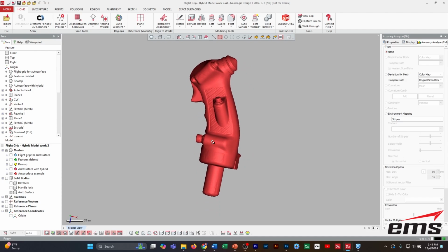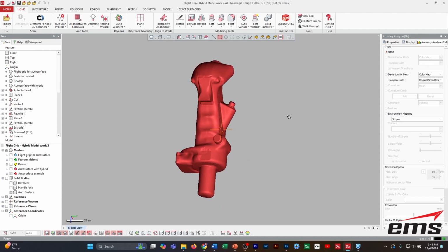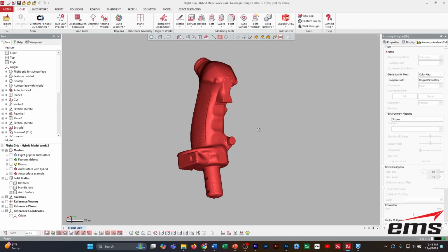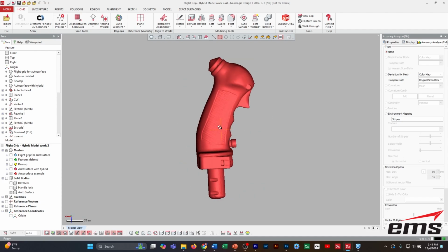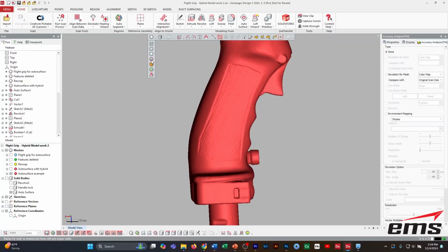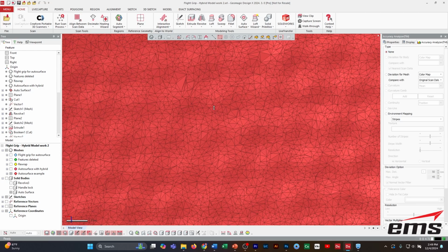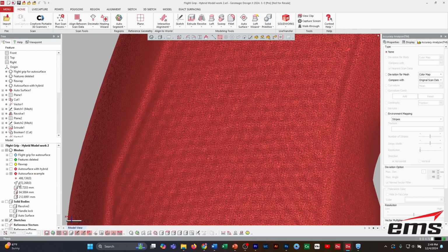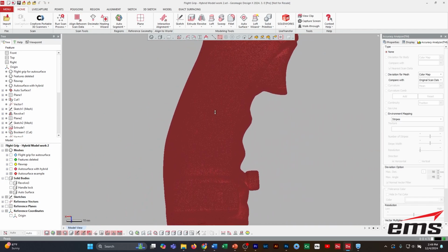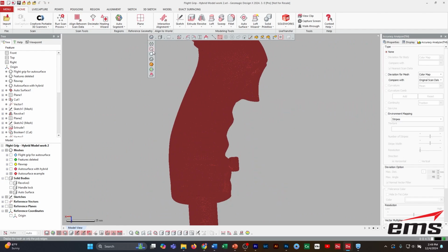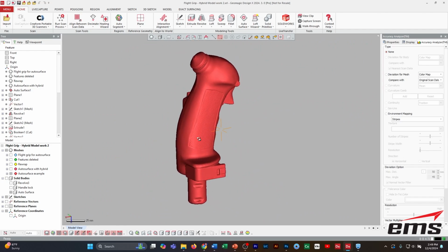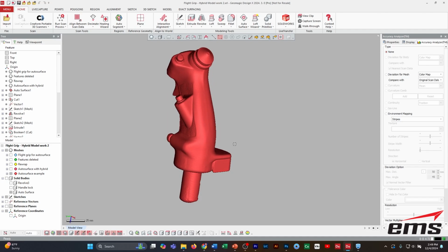Now you've got some editing tools. You can go in and smooth and do some different things. But basically, when you create an auto surface from a mesh, it is going to be an exact copy, like I said. So as we showed before, here's what your mesh looks like. And if you zoom way in, you can see it's just a lot of triangles. About 972,000 triangles make up this mesh. And again, this is not something you can use in your CAD system, and it's not something you can typically use in any kind of manufacturing system.